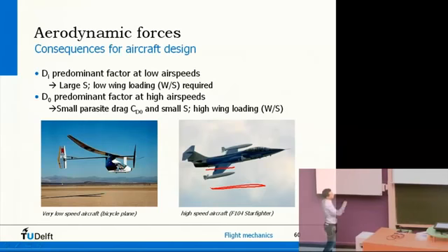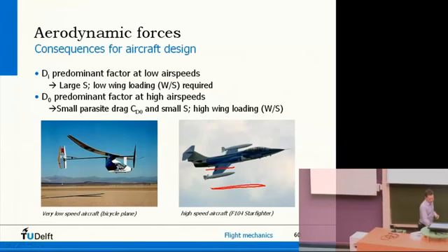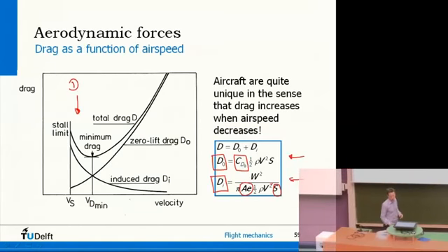So there you see that this aircraft on the left has a completely other wing. The wing itself is designed completely differently. And that's simply because of all these terms you see in this induced drag relation. So aspect ratio, Oswald factor, they all play an important role.